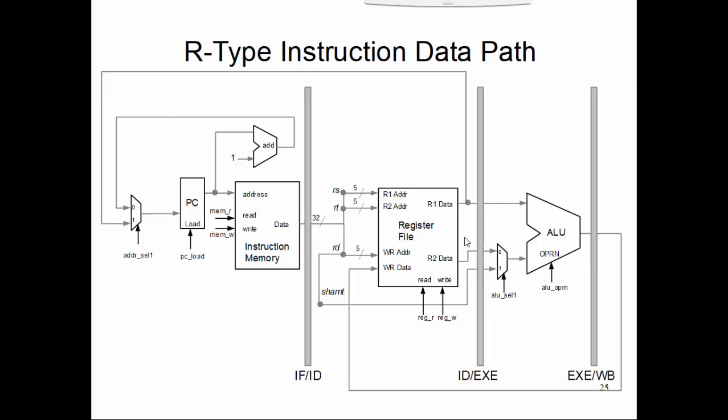What we do with this partition is, at the partition boundaries, we make a bunch of flip-flops, and the data flows through this bunch of flip-flops from one stage to another. So in the boundary of instruction fetch and instruction decode, we make a bunch of registers there. A register, to be precise, because a flip-flop cannot be used directly. We need to have control over selectively loading some data, not loading some data, etc. But the point is that